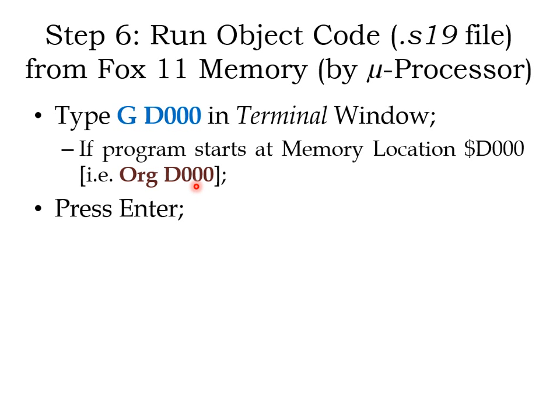You'll be using probably some of it, right? You will have to start from somewhere. It doesn't mean that you always have to start from address 0000, right? You'll be starting from somewhere else. We'll also explain why. Let's say this means your program actually has started from this address. That will be also always given in the program, okay? This line will be always there in the program, and this line indicates actually where your program started. From this line you see the program has started from D000.